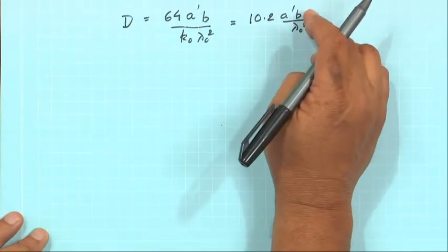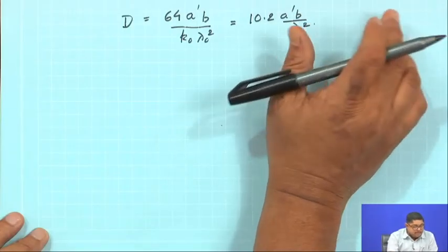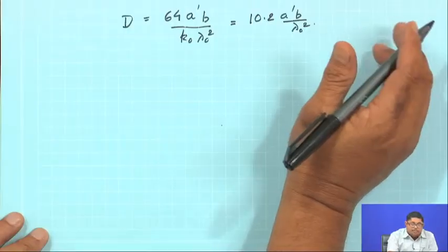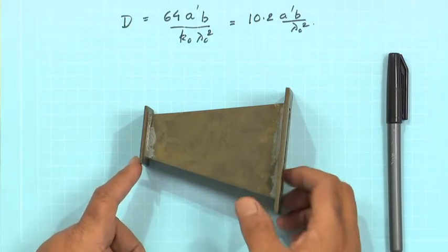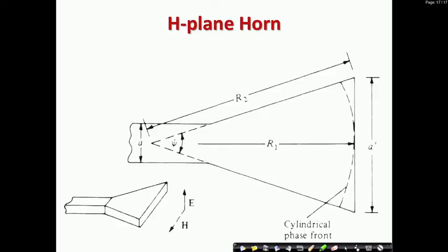So, this is your physical area, the effective electrical physical area. So, actually the directivity you are getting by this horn is 10 times that. And you remember that at microwave frequencies the gain of the horn is essentially equal to the directivity, as losses are negligible. Now, if the horn length is fixed, but I want a higher gain, then it can be obtained by increasing the flare angle to some extent, which will cross that pi by 4 restriction on the phase error. But with the increase in the aperture, because if I increase the flare angle the aperture will increase, the extra gain somehow compensates for the loss from the phase error.